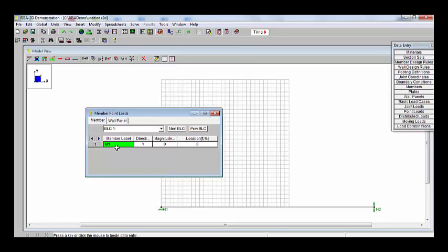This member label corresponds to this member, since this is the only member in our system. The location corresponds to either a percentage or an actual distance in feet along this member. Just like in joint loads, in order to get a loading that is pointed downward, we would have to put a negative sign in front of the number. So for this, we'll put -20.